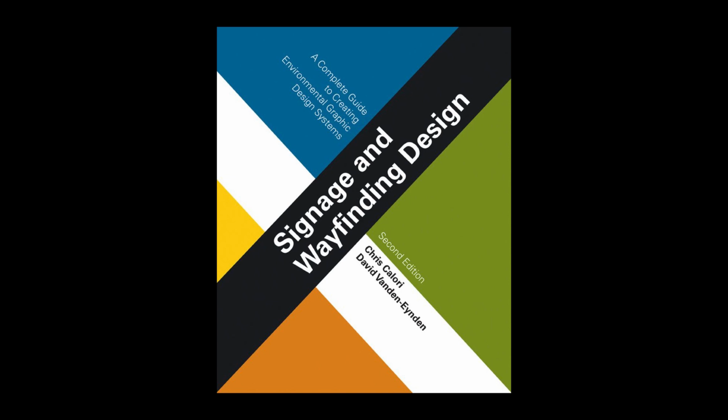Responses to information requests. Responses to information requests are just that. Bidders sometimes have questions or need clarifications about the design documents, although generally not too many if the EG designer produced a thorough document package. These clarifications can come up in a pre-bid conference, where the EG designer is present to respond, or in the form of official requests for information, RFIs.